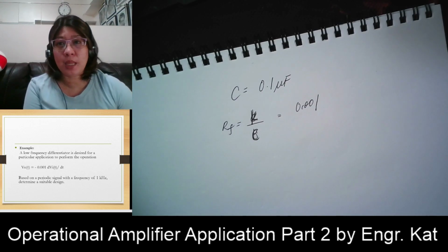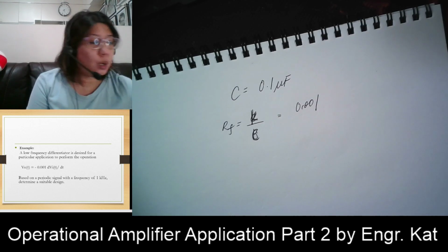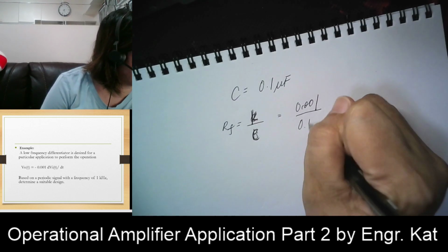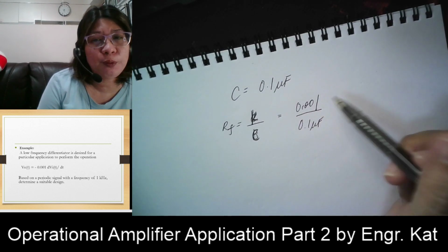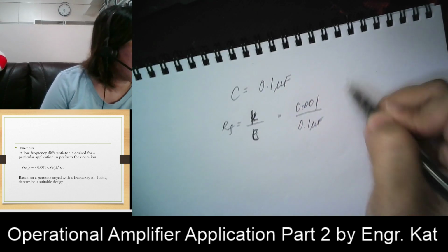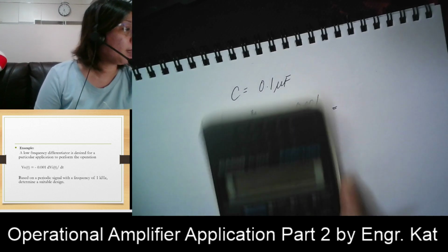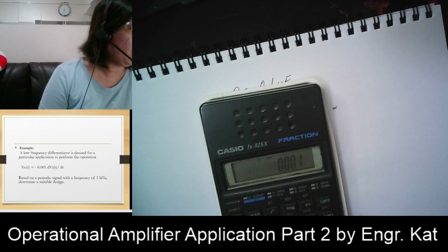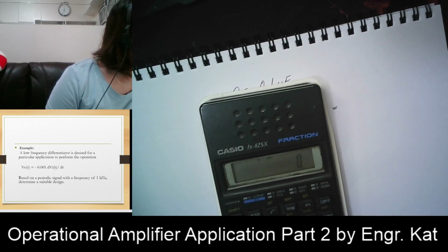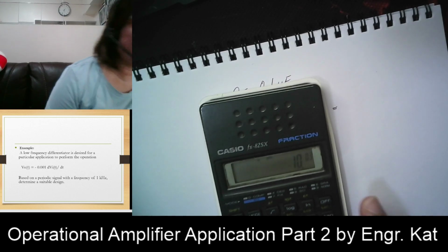No need to place the negative sign; it just signifies that your input is applied at the inverting terminal. Divided by 0.1 microfarad. Where does the 0.1 microfarad come from? I just chose that. So solving for that, 0.001 divided by 0.1 microfarad gives you 10 kilo ohms.